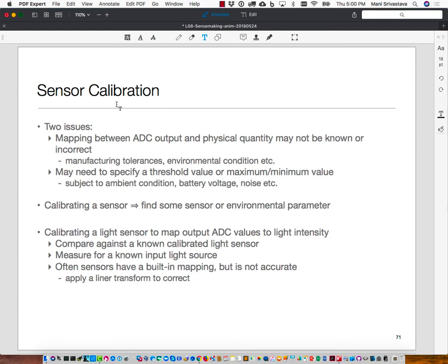So if you believe your sensor is not working correctly, then you compare its reading against something reference and find that mapping. So calibration is an important thing, and a very common model which is typically used is simply a linear calibration. We basically say, look, the underlying phenomenon and the reading are linearly related because much of the circuit is amplification and some gain and stuff like that. So it's a linear structure, but it doesn't have to be.